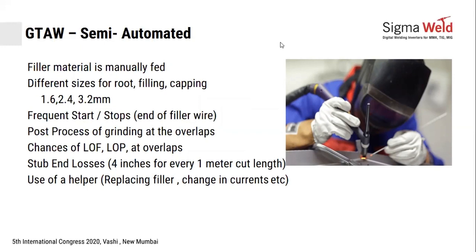Now at these places where you stop and start, you have an overlap where you have to restart, and that is where the problems of lack of fusion or lack of penetration usually occur.